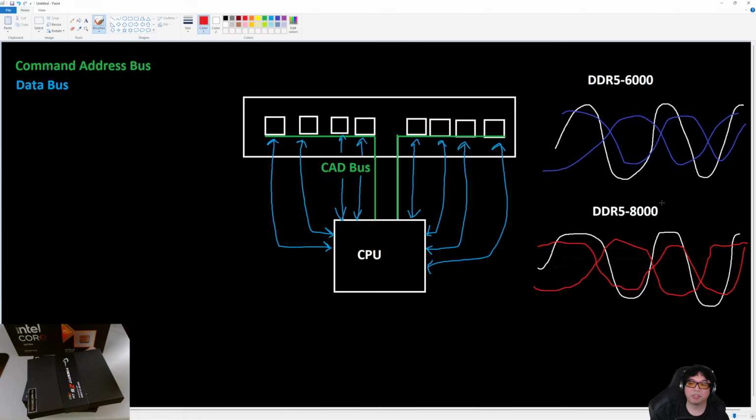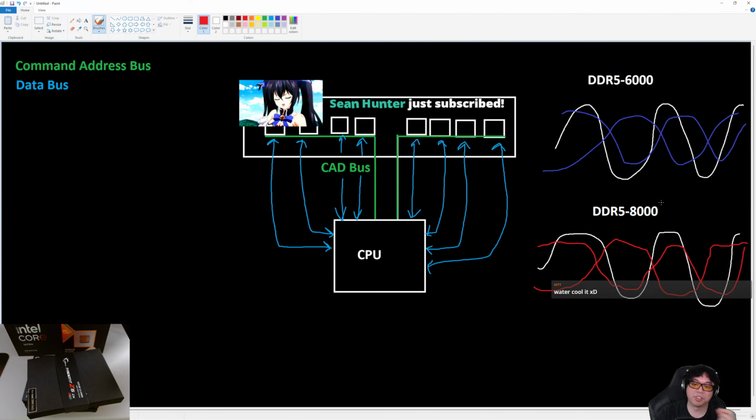Well, one of the things would be colder temperatures. Active cooling on the memory, for example, is a very easy way to stabilize the system, because if the memory is running really hot, you could end up with instability. The other thing is lower voltage. Simply running lower voltages, meaning better binned memory that can achieve higher switching frequencies at lower power, also means that you get a more stable system.